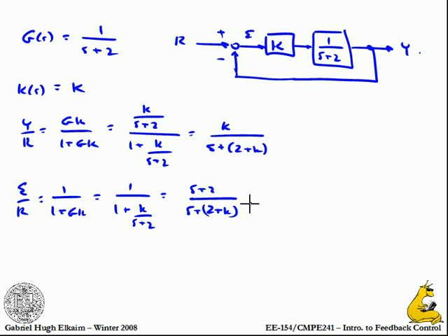All right. So just to note that my tracking error in steady state to my input is different than my error input. My error is in steady state. Okay. Because in steady state this is going to be K over K plus 2, right? Which as K gets big looks suspiciously like 1, right? Whereas this is going to be 2 over 2 plus K, which as K gets big is hopefully going to go to 0. Right, so that hopefully should make sense to you.